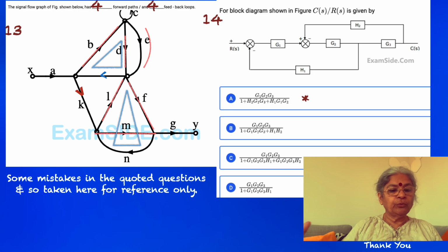So there are only two paths leading after A. So that's the next one. A, K, L, F, G, A, K, M, G. So four. In all other cases you encounter a roadblock. So that's all that's there. So four feed forward paths.